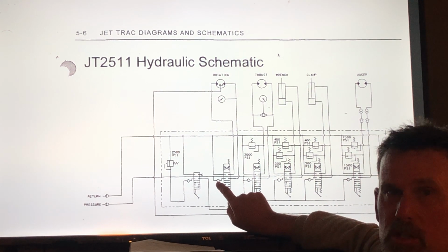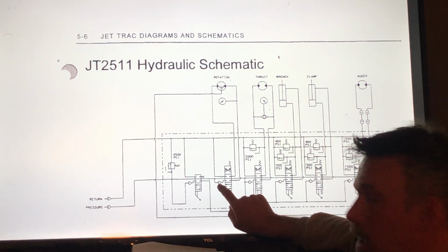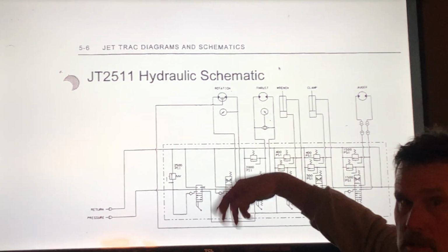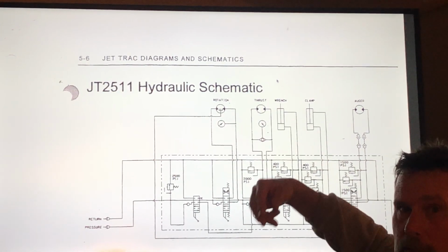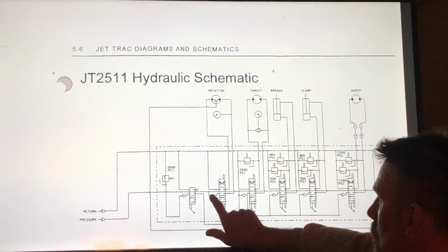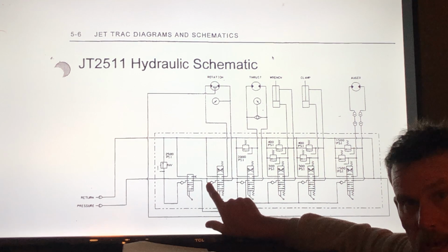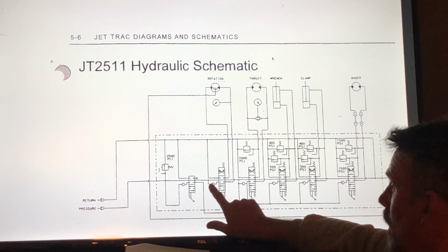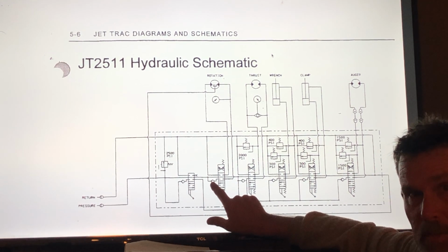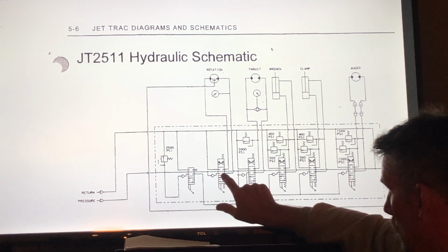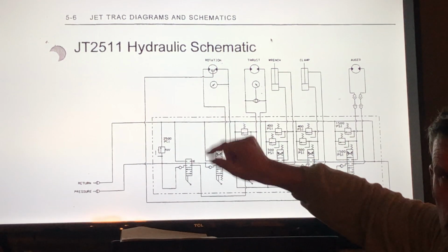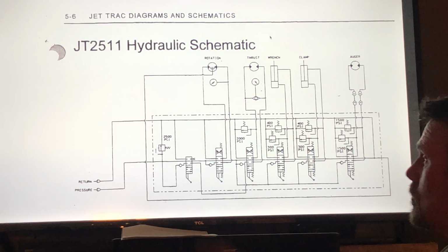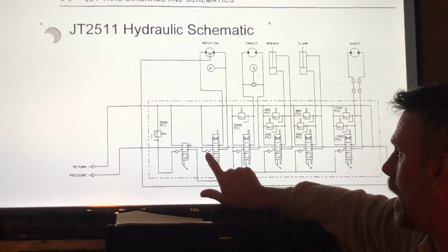But the load check is slammed shut by 2000 PSI. So the pressure here starts to build from 0 to 100 to 500 to 1500 to 2000. Still can't get through, but as soon as it hits 2001, it can overcome the check valve and start to push into that work port, and our bucket goes up, right?